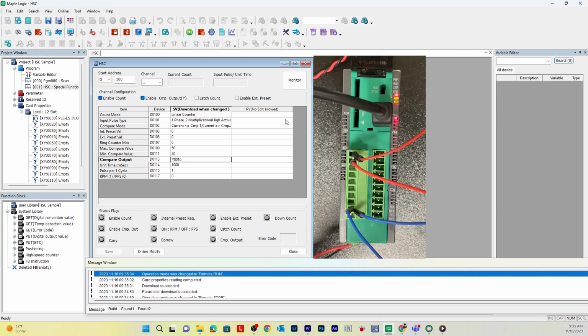And you can see my camera feed, and I'm going to press monitor. And as you can see, the compare output is on because we are actually below the minimum value, which is at 16 right now. And I'm going to send 24 volts, and then I'm going to send a pulse. So now it's between that range. I'm just going to stop, and as you can see, it's been within that range of 20 and 50. So an alarm has not gone off because it's in that range.